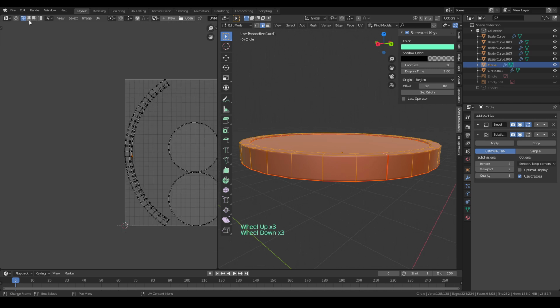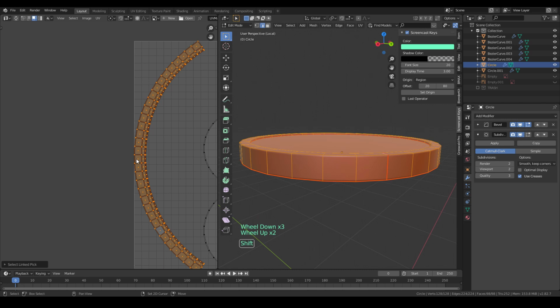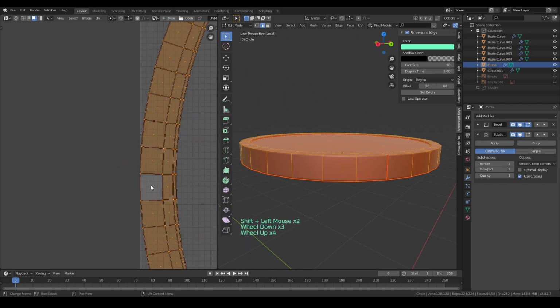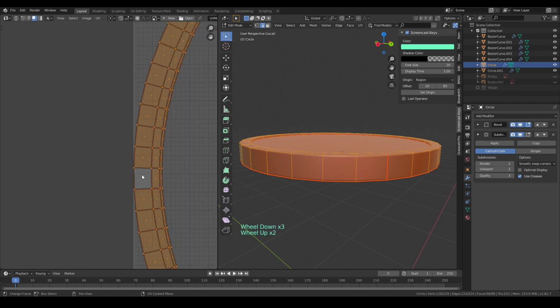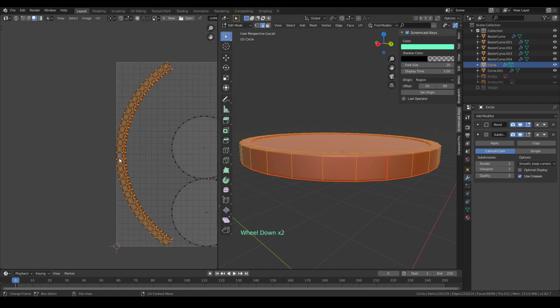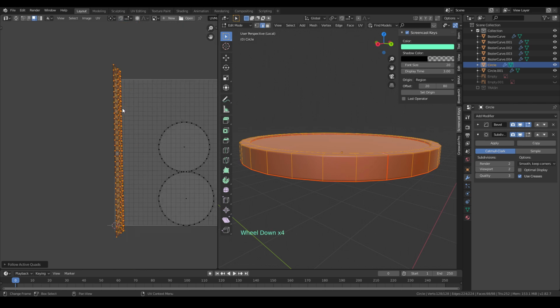So what I'm gonna do is I'm gonna choose the face selection and select all, and then I select the most rectangular face here, and usually it's in the middle. And then right click and follow active quad, and then it will somehow fix the issue.